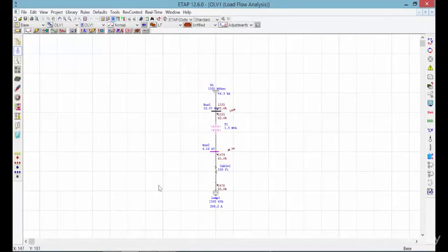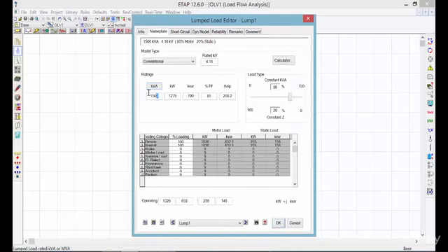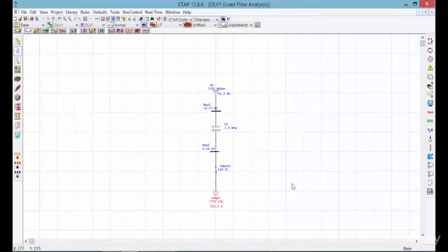Now again, we can play around with this a little bit more, and this time we can double click and change the 1500 to 1700, a little bit more than before and a little bit more than the capacity of the transformer. So now this time, if we again run the load flow analysis, the color of the transformer turned red.